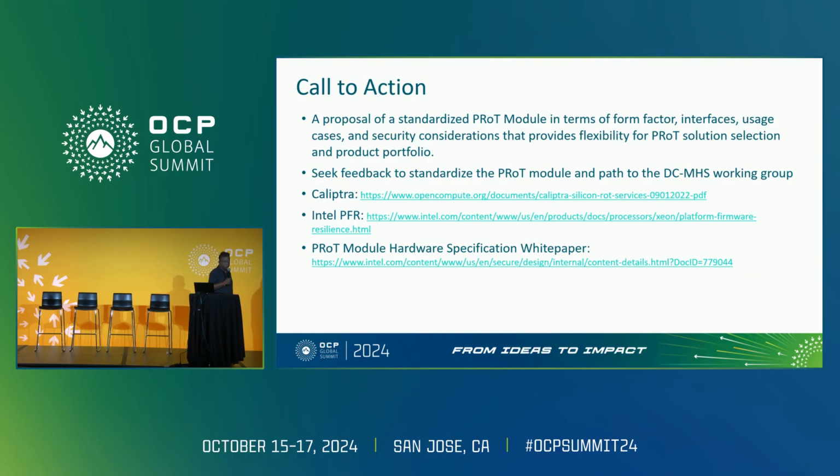Thanks. Hello, I have a question. So the PFR is designed as a module. Can I just design a fake module and then bypass all the security checks? No, because there is some I2C communication, the handshaking with the BMC that we have defined here. So you can do some handshaking, key exchange. You can also have a PFR presence signal that can be authenticated by any entity. You're right, you can do that if you were, but we have some checks there. Okay, thank you.